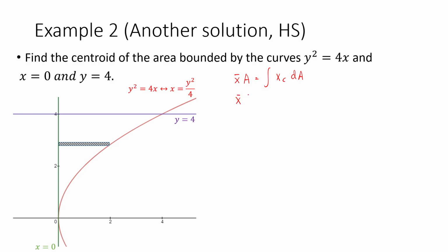So again, since we are using the horizontal strip, this is from y1 to y2, x sub c, x right minus x left dy. So again, notice that this time we shift. Earlier, our midpoint formula was coming from bar y since we were using the vertical strip.